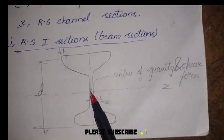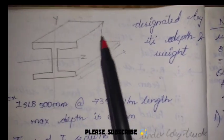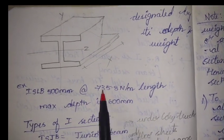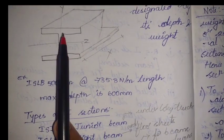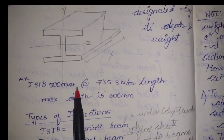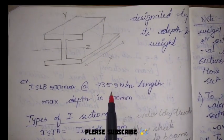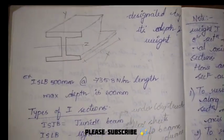This is the center of gravity and the shear forces. This is the I section representation. Whenever we are showing the I section, we'll be mentioning this one: ISLB 500 at the rate, this would be given. Whenever we are selecting any I section, this data would be given, where this 500 mm shows us the depth of the I section, and this is the weight per meter length, whatever the Newton value is. This is the designation of the I section.